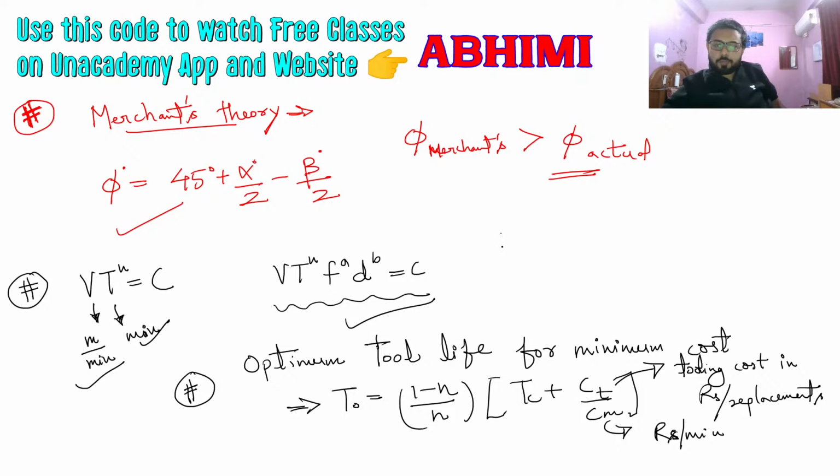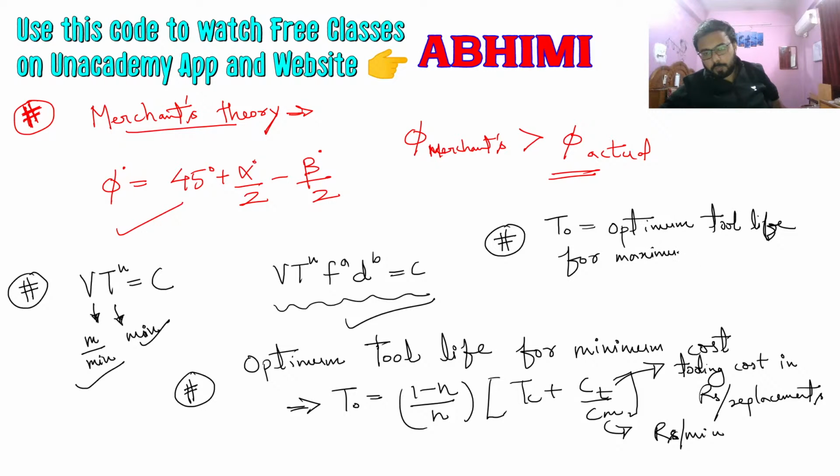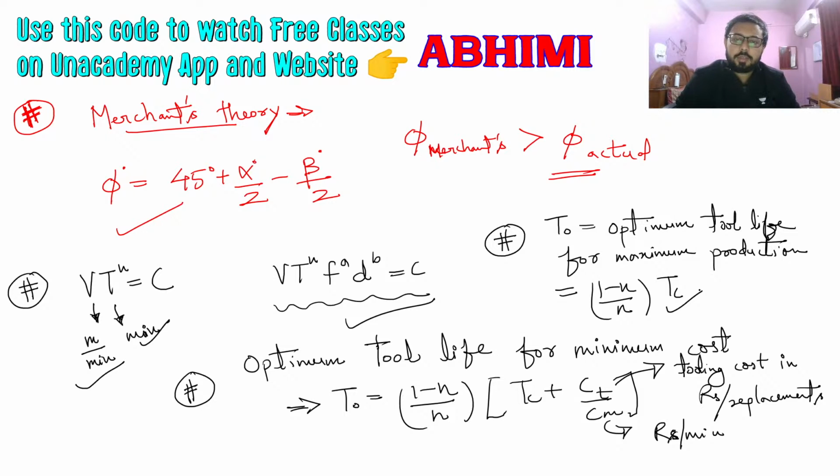But if optimum tool life is asked for maximum production, then it will be (1 minus n) divided by n into Tc. It will be this simple. So again, when you get this optimal tool life, you can use it in Taylor's tool life equation to get the optimum velocity for that condition. So that will be it for the discussion of optimum tool life formulas and also Taylor's tool